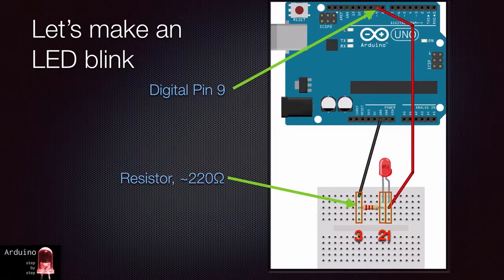Now here is a tricky part that has to do with connecting the LED in accordance with its polarity. Take the LED, find its long leg, and plug it into an empty socket in column 1. This socket conveys the positive voltage. Plug the other leg into an empty socket in column 2. An easy mnemonic rule to help you remember how to connect an LED is that the long leg must be connected to higher voltage.